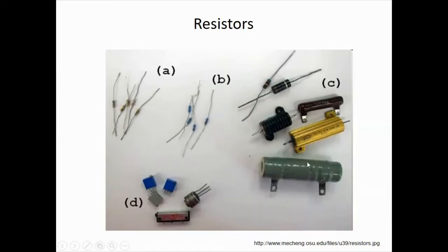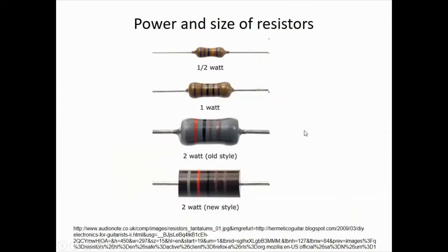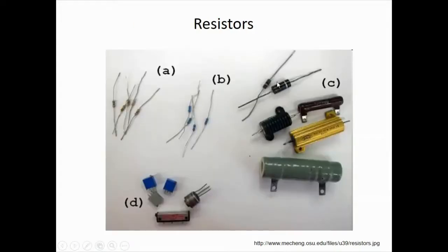So depending on the application, one would use different sized resistors. Here are the standard resistors, and these are the capacities. The resistors you use in the lab are either quarter watt or half watt. These are slightly bigger, they are all 2 watt. This is half watt, this is 1 watt. These are many watts.